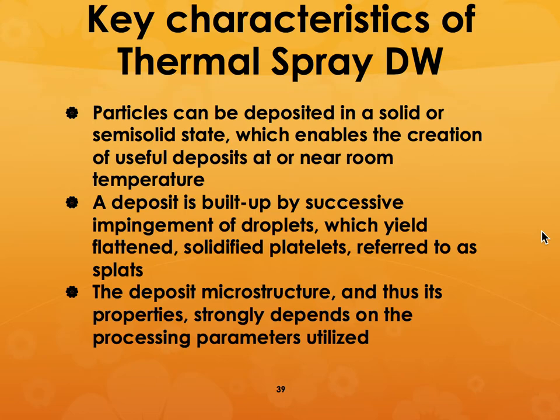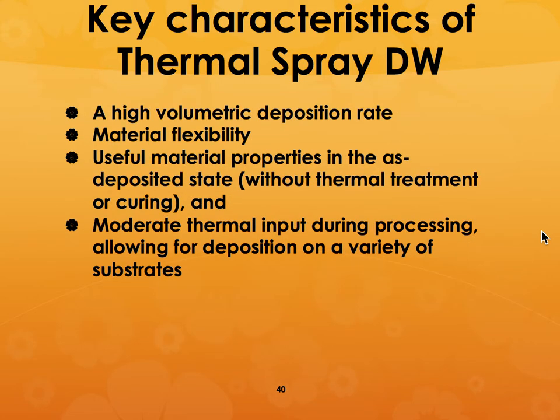You can deposit them in solid or semi-solid state. These materials can be deposited at or near room temperature, as droplets or solidified platelets, and these solidified platelets are called splats. So you are splatting the material onto a substrate, and your processing conditions and parameters will strongly control the deposit microstructure and its properties.